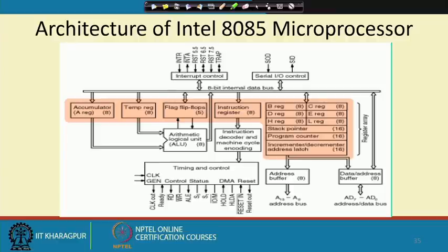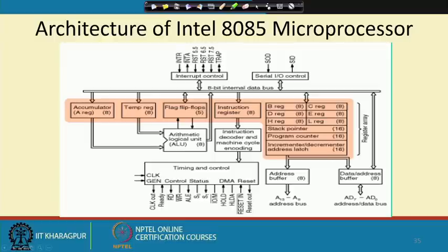If you want to tell the processor from the outside that something special has happened and that has to be taken care of, you use an interrupt. For example, if this 8085 microprocessor is used for controlling the operation of a plant, and a smoke detector detects some smoke, it can send an interrupt to the processor telling that some abnormal situation has been detected.